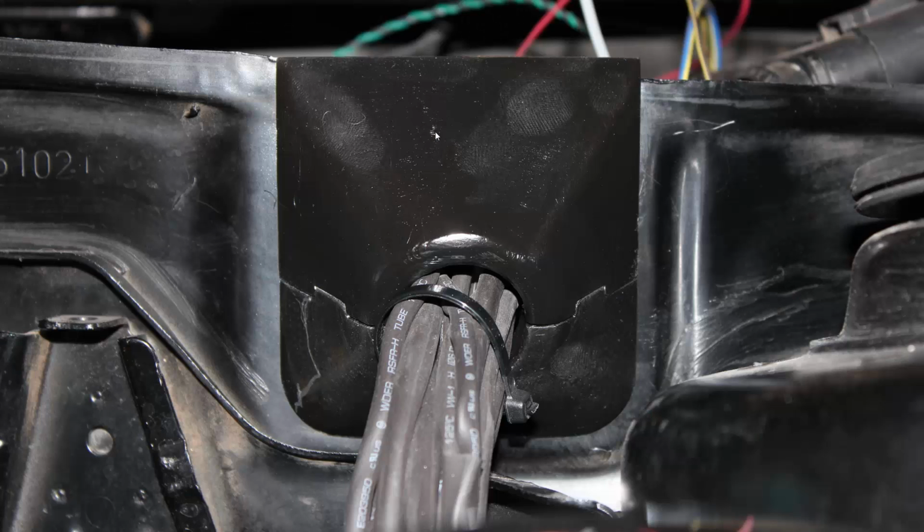And then here's a close-up shot of some of the issues. You can see in the top right corner, my tape template didn't account for the drop in height, so that doesn't match up. That's actually going to be a problem when I go to install. There's a seal that goes along the top there that seals against the hood of the car. That's going to be a problem. So I'm either going to have to cut that down or grind it down or redo the design.